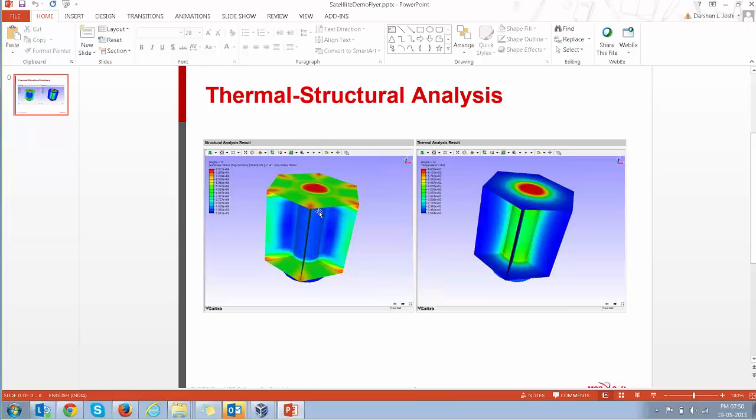These circuits are placed at the ends of this cylinder that is at the core of the satellite, and the cylinder or the core of the satellite is connected with the fins and the top and bottom sections of the satellite. The heat is conducted to the peripheral parts of the satellite, and there is also radiation to outer space from the peripheral parts, which is modeled by the NASA ambient space option.